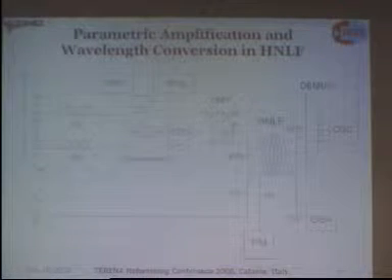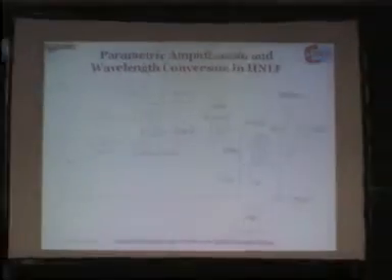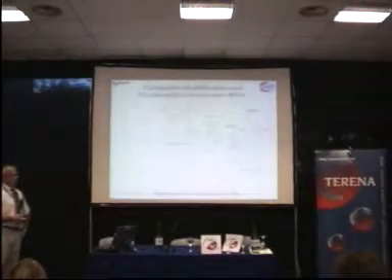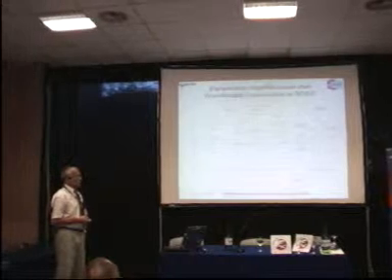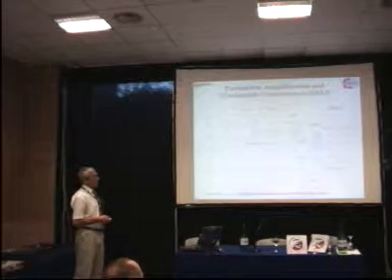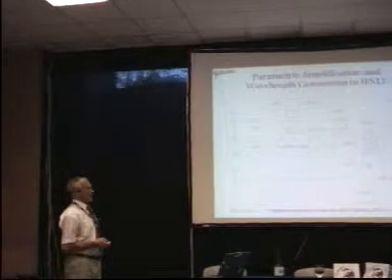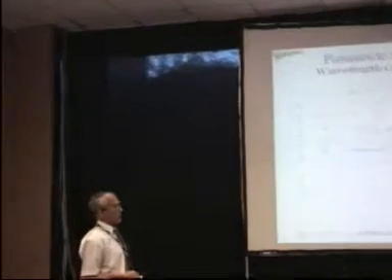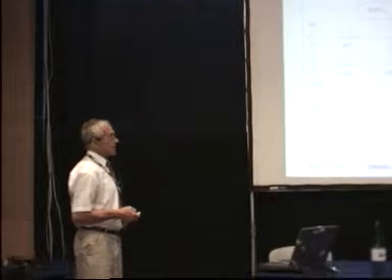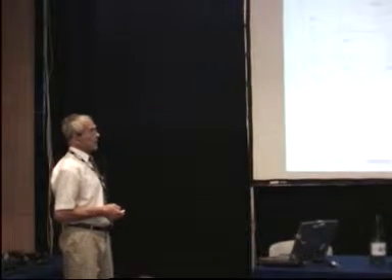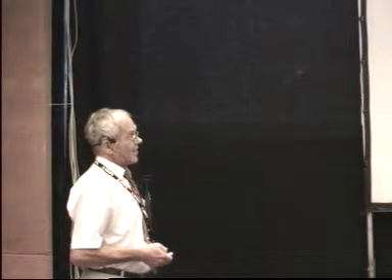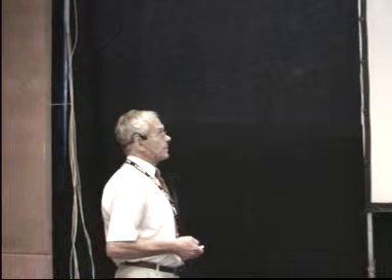So the nonlinear coefficient of a standard fiber is about 50 times lower due to the higher content of germanium and smaller core size of the highly nonlinear fiber with respect to standard fibers. So the main purpose is to increase the nonlinear refractive index of this special fiber to achieve as high as possible four-wave mixing or cross phase modulation in this highly nonlinear fiber.